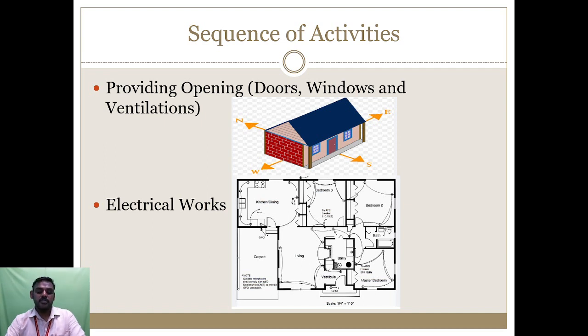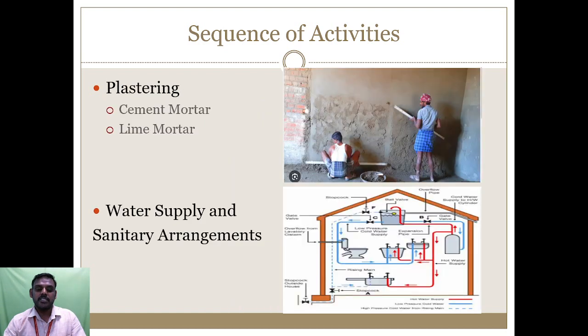After the electrical work on the reinforcement, only then is roof concreting possible. After this, the wall conduits also have to be cut and the electrical fittings and switch boxes placed. After that only will we go for plastering works.